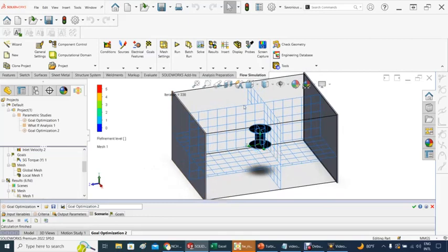If I increase the global mesh from 3 to 4 to 5, then that will definitely increase the time to 20-30 minutes per run, and that's a lot, you might have to leave it running overnight. I'm using a computer with an i5 microprocessor, so it's not the fastest machine in the world. It gets some of the job done, but I still need to be careful with that.